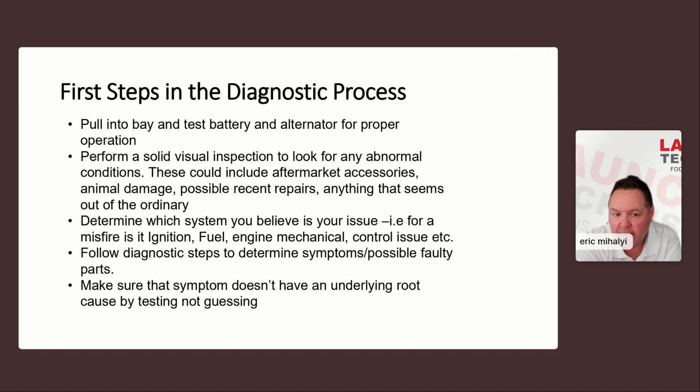Yeah, that's where you go, and then you're just going to follow your diagnostic steps from shop information. Basically, you've got to start doing general tests or the simple tests before you start getting into pinpoint tests. That's one of the biggest problems I see: guys want to break out their meter or their scope and start testing and looking at signals. 9 times out of 10, it's probably a simple problem. Voltage drop or a bad battery or something. And really, it's quite simple.